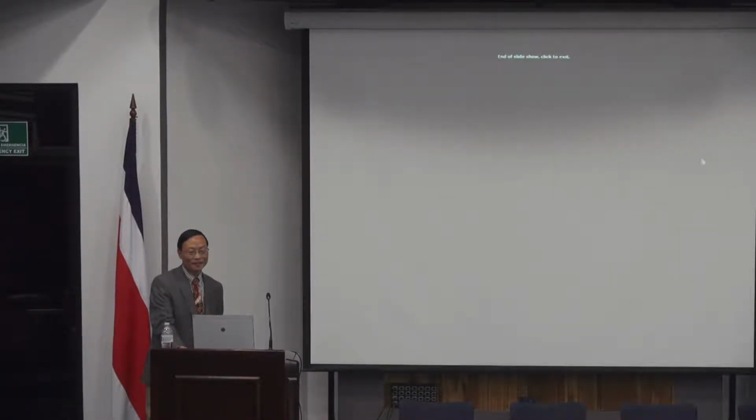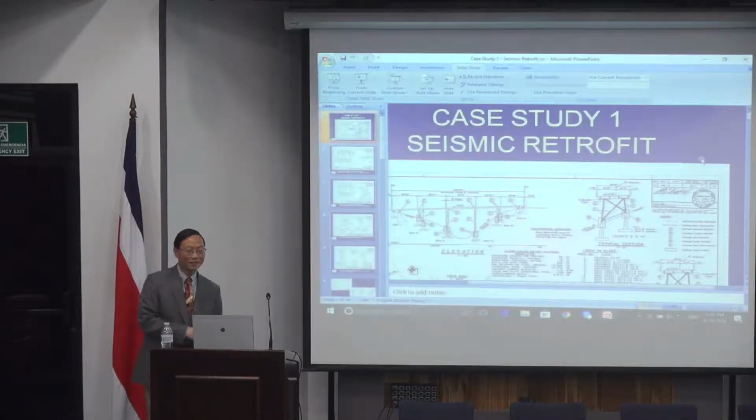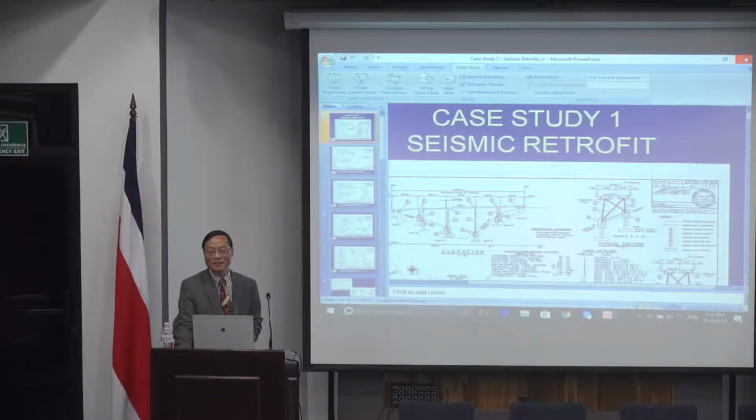If you have headroom, you may just drive regular steel piles. If not, you may just do micro piles. Micro piles do not need a very big equipment with high overhead clearance. You just do like that. Again, these are very typical scenarios.